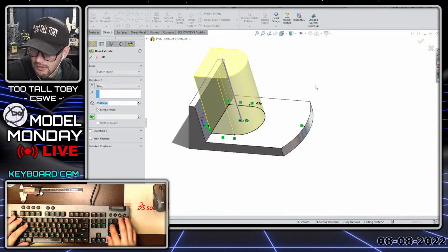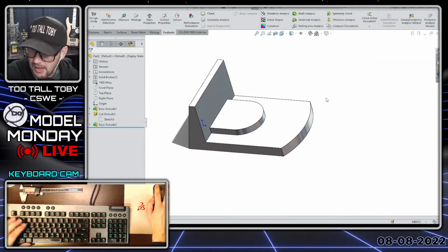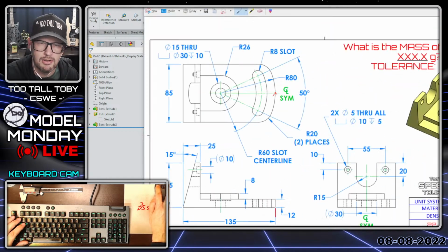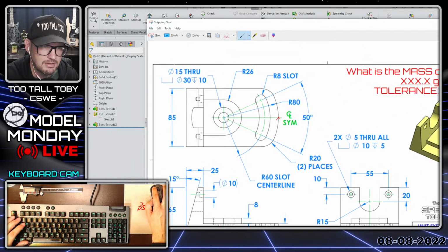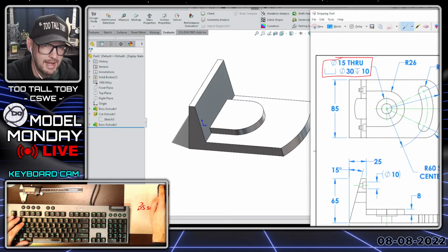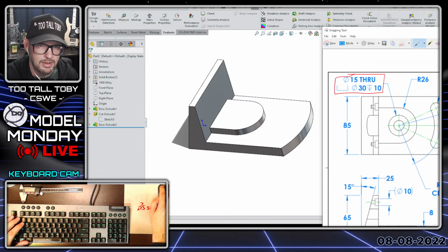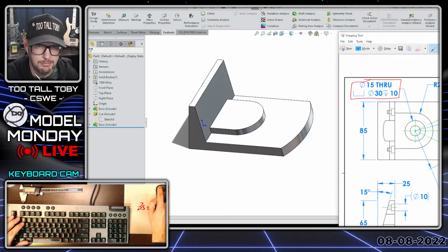S key, extrude, and that's going to come up to a height of 8, and then that's going to have a C-bore going through it. So always good to learn how to read the C-bore information. I know this is a little bit of an advantage for the SolidWorks crew versus people that are using other CAD systems, but when you're looking at a call out like that and you're working in SolidWorks, you can basically just type in the information in order.